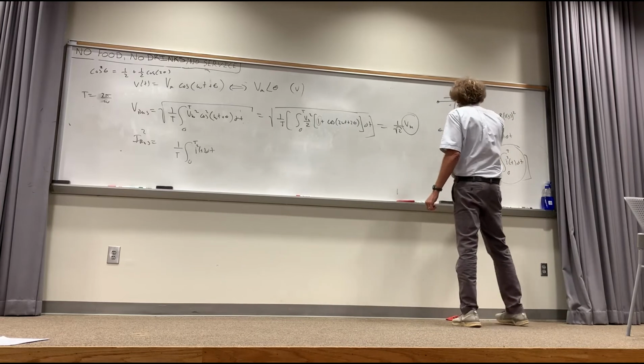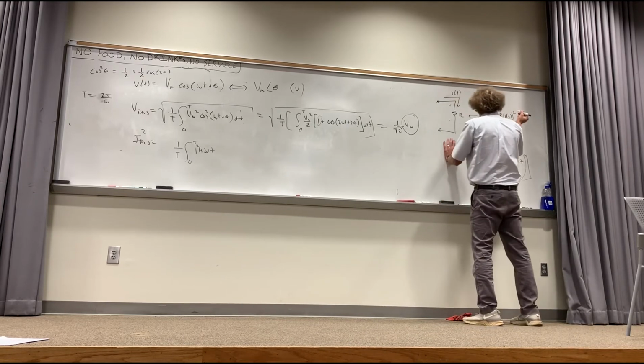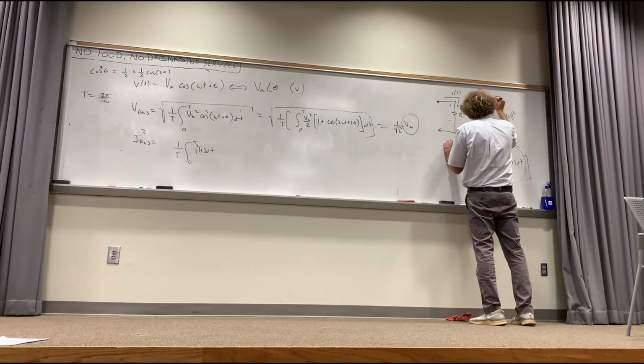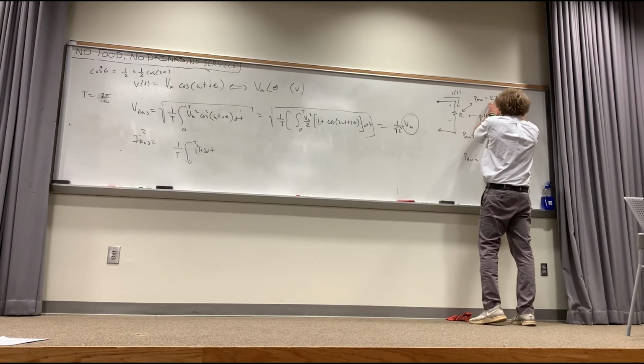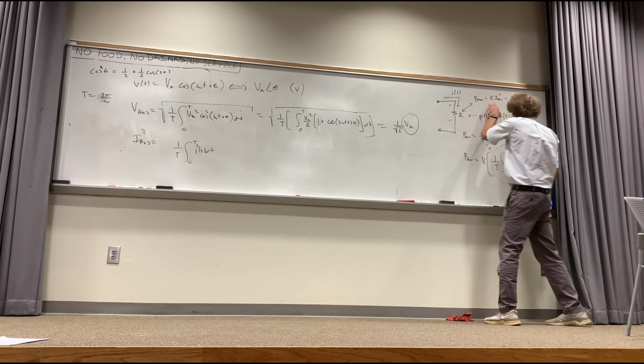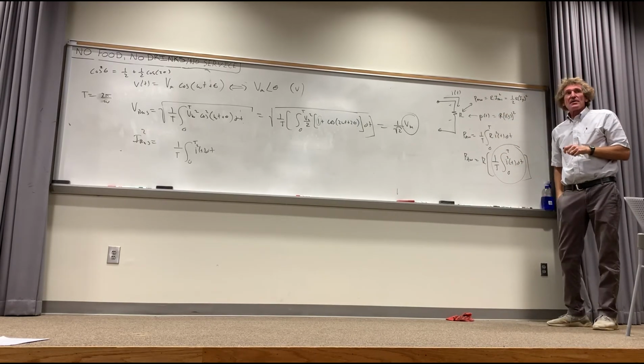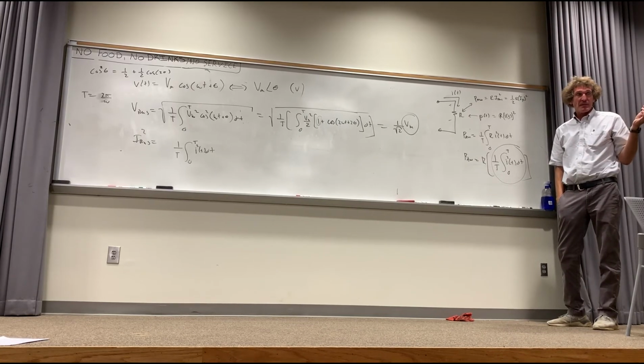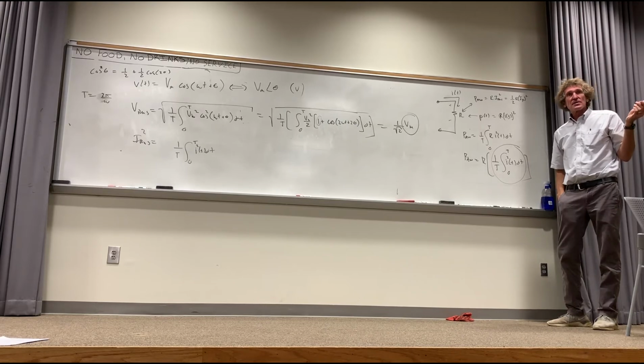And the average power in a resistor, P_av, can be given as either R times I RMS squared, or as 1/2 R times I peak squared. The RMS value and the peak value are related by 1 over the square root of 2. Got it, everyone? That's the thing you take from this. We'll be using this a lot.